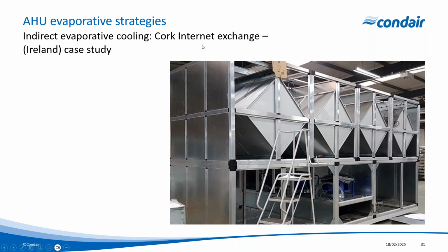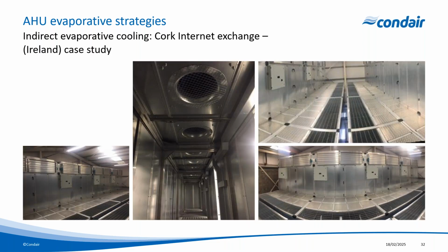And then on the other side, outside air, evaporatively cooled, supplied through the first heat exchanger, through the second heat exchanger, and then exhausted out, and then just mirrored on the other side. And here you can see some additional photos of the air handling design. So quite an impressive design here.